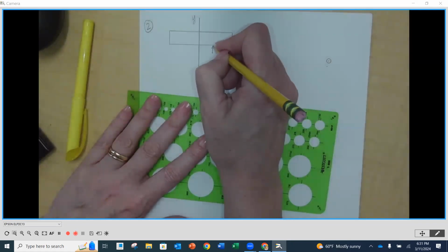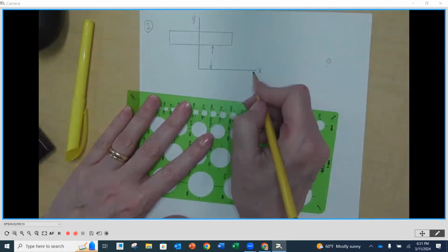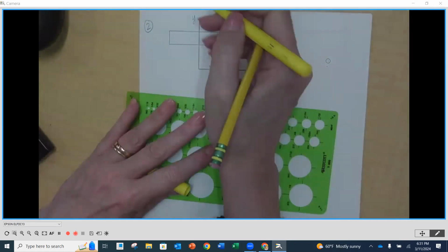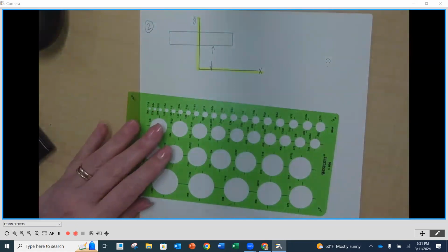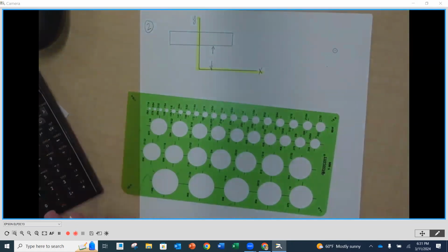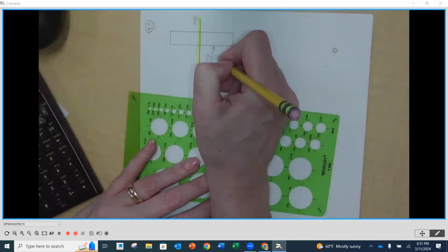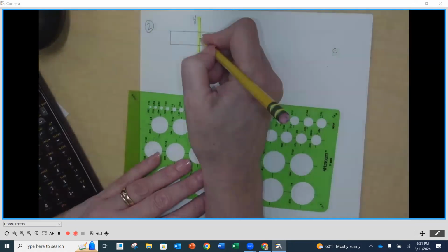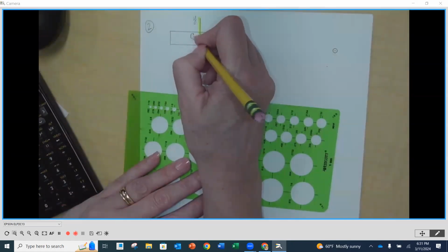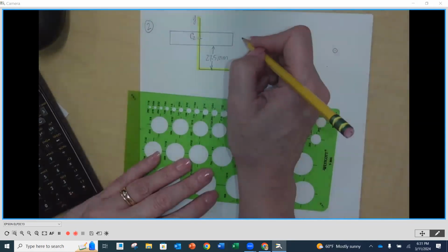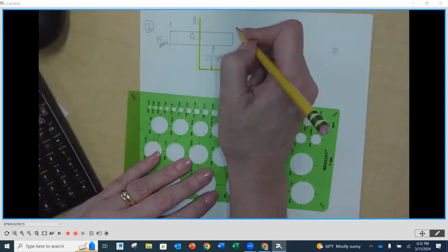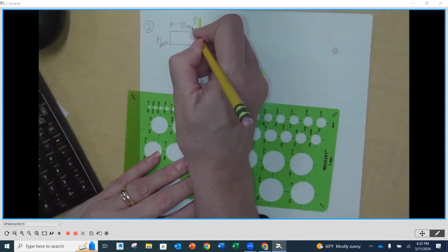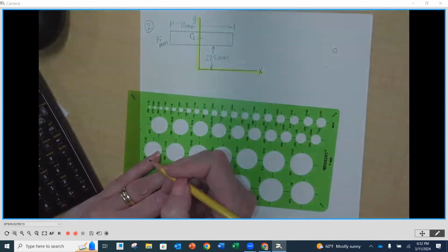I know that the distance from my x-axis here, which was my reference axis, my yellow, is going to be half of 55. What's half of 55? 27.5, exactly. So 27.5 millimeters, we're going to put there for right now. The centroid of shape number 2, I know this to be 15 millimeters. And I know the overall distance is 70 millimeters at the top here.